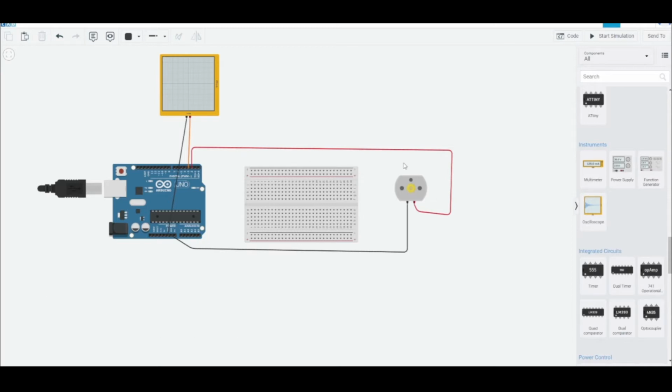And the other one is when we turn off the voltage on the pin, the inductive load will still induce a back EMF that'll run through the line and back into the microcontroller, and it might destroy some critical components in there. So we need a different way to drive our motor.